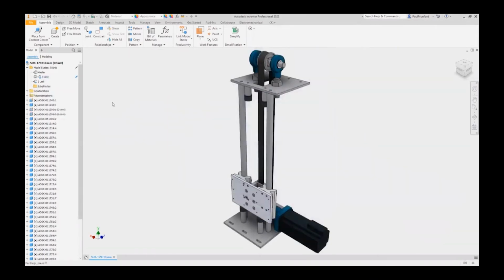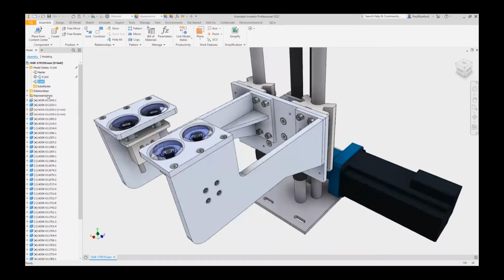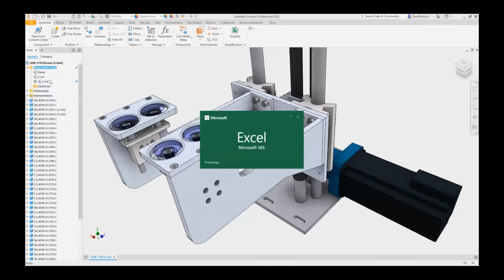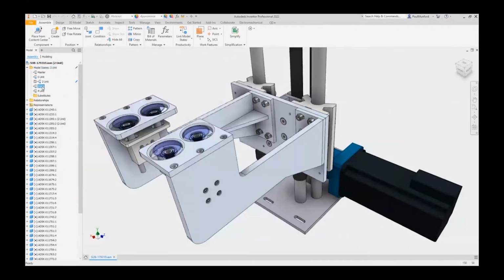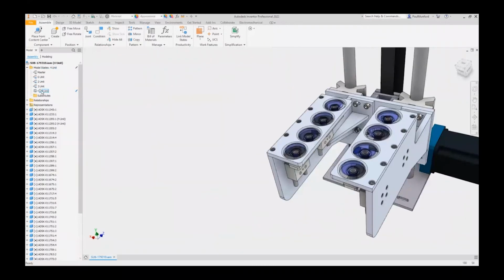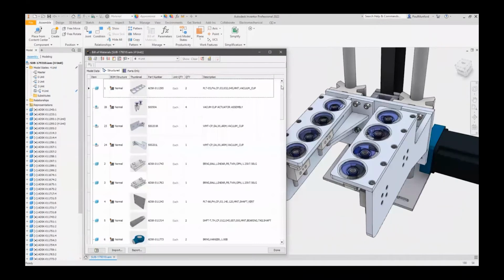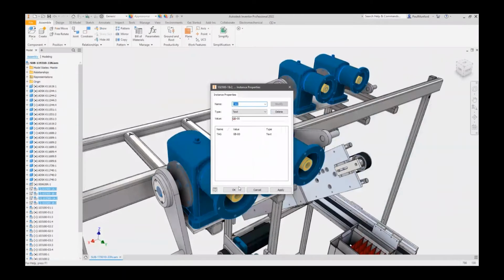The new model state records the suppression state of components and remembers model state settings of subcomponents. Multiple families or variations of a design can be quickly created using a spreadsheet, as we might have done previously. Each model state also captures unique part properties and quantities to track the number of items required in your bill of materials or parts list.